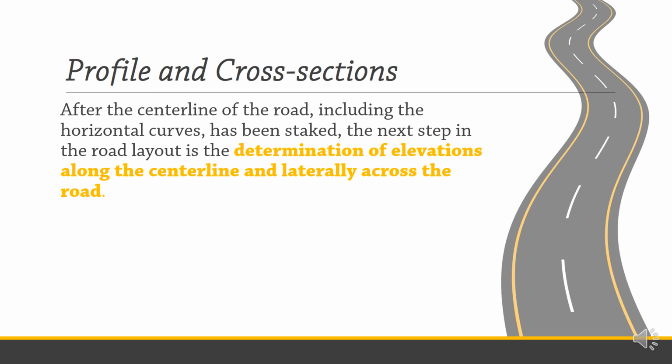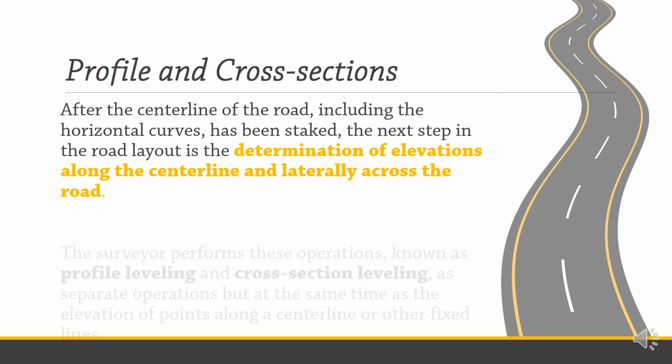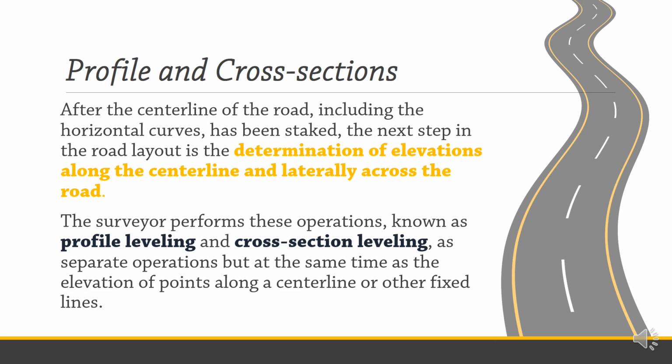So, after naman, gagawa ng profile and cross section. So, after the center line of the road and nag-stake na, it is now time to determine the elevations along that center line and across the center line. So, the surveyor performs these operations known as profile leveling. So, profile leveling is, say, magsasurvey siya. So, leveling is about taking elevations.